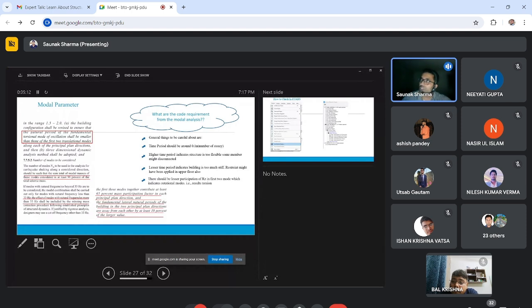If you haven't read structural dynamics yet, just assume that there are a number of modes, which are the deflection patterns showing how the structure reacts while vibrating during seismic force. There are first mode, second mode, third mode, and generally ETABS by default analyzes 12 modes. Let's assume 1, 2, 3. These first two modes should be translational.